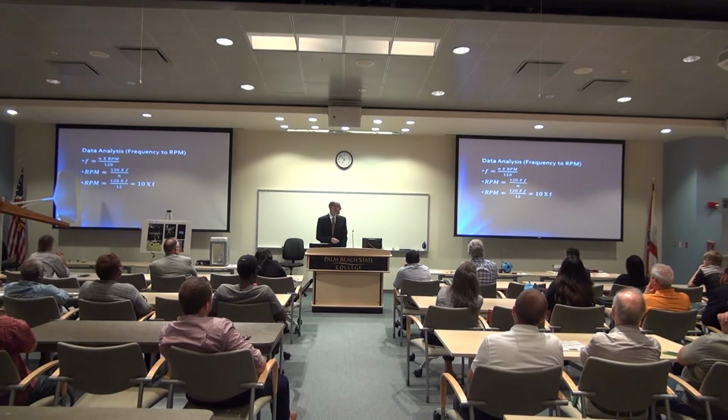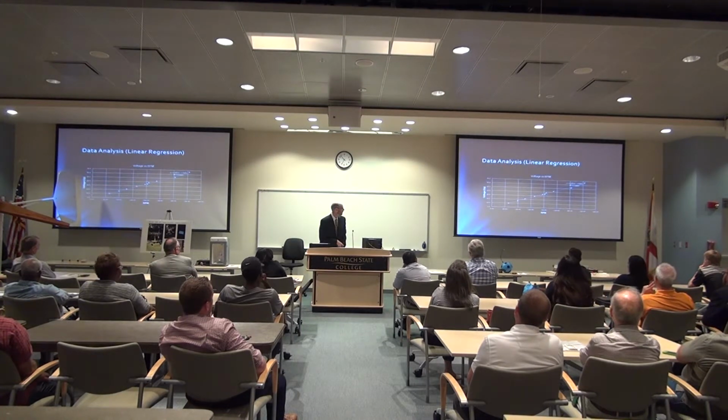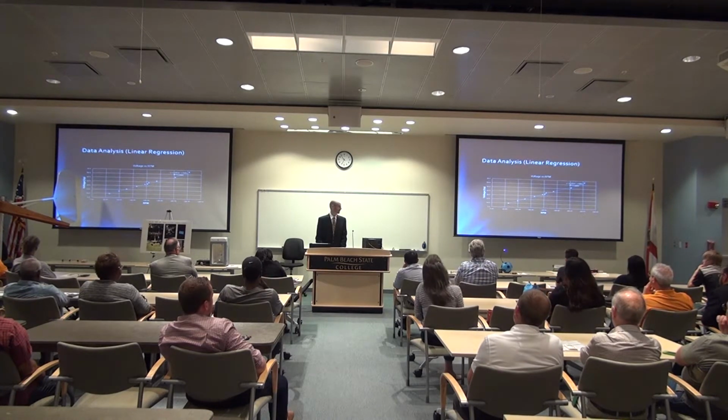And the reason that you need to know that is because of the performance of the wing. If your alternator needs to spin at a certain speed to produce power, and it can't make that speed at low wind speeds, you're not going to be producing any power. So anyway, I plugged all of my frequencies and voltages into Excel, and there's a beautiful linear relationship between RPMs and voltage. And I discovered after plotting all this data out that I made a mistake and recorded this data with a significantly larger load on the alternator than it's designed to run with. So I need to repeat this measurement in the future. But it did let me estimate that my alternator should start producing power in wind speeds of 7 miles an hour. So very big amounts of power.